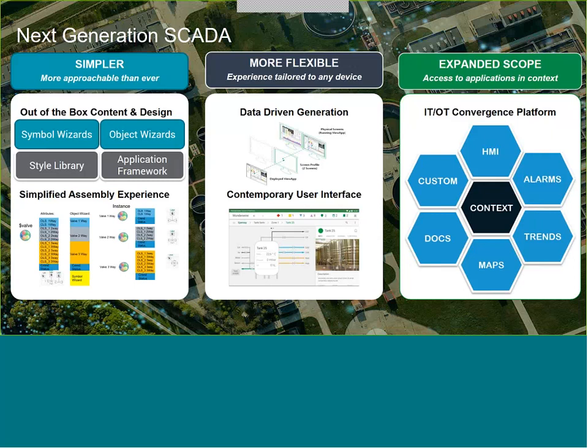If it's part of a faceplate that belongs to your more detailed view of your particular process, it will automatically put in the process data for that particular detailed information. So for a tank or something like that, a particular asset that you might have on your plant, you'd see all of that process data automatically inside of that trend. But not only would you see that, you'd also see any alarms that have occurred as halos over the top of that process data. It'd also show you who's acknowledged it, when they acknowledged it. All this type of information is now built into that solution.